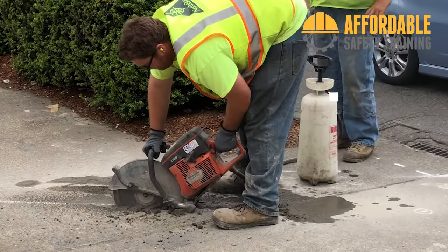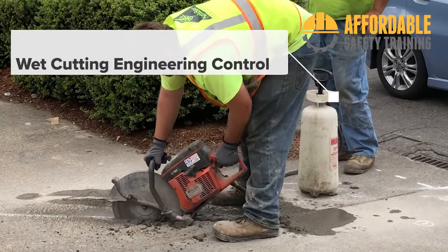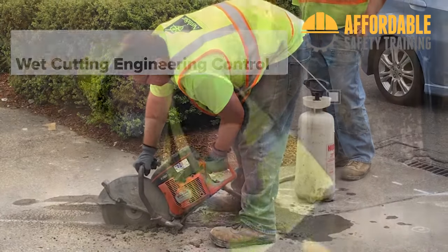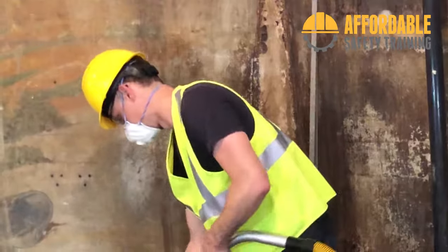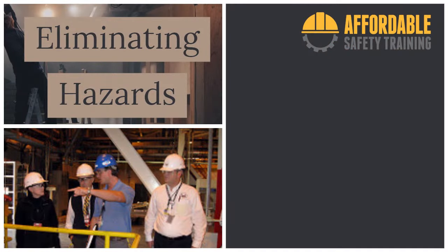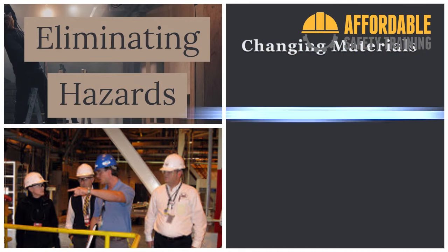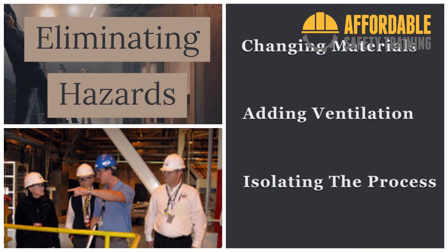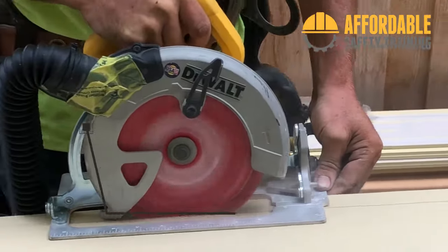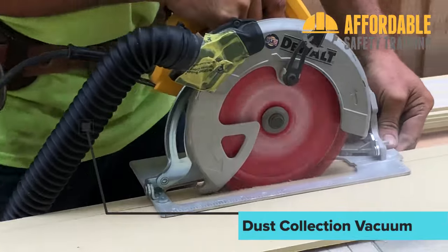The preferred method for dealing with atmospheric hazards is eliminating them with engineering controls. Requiring PPE is always the last resort, to be used if the hazards cannot be eliminated. Removing the hazard can be accomplished by changing materials, adding ventilation, isolating the employee from the work area, or many other methods. If it is not feasible to eliminate the hazard, then respirators can be used. Always try to eliminate the hazard first, before you require employees to use respirators.